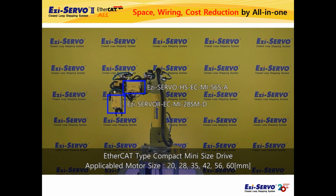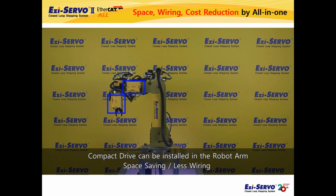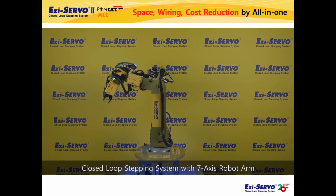In addition, Ezi-SERVO II EtherCAT Mini is applied to 2 of the 7 axes, for the hollow axis and the gripper axis. Because the mini drive is small and lightweight, it can be installed directly on the robot body. In other words, because the distance between the motor and the drive is very close, the motor and the encoder wires would be very short, too.